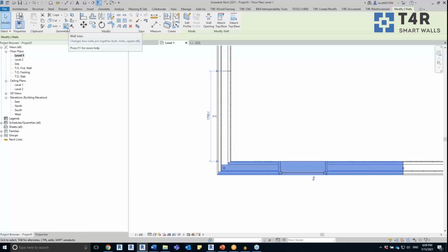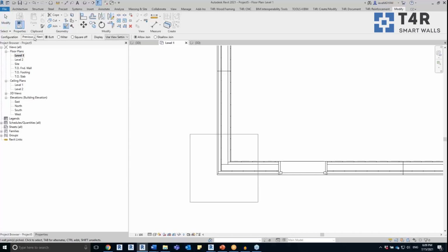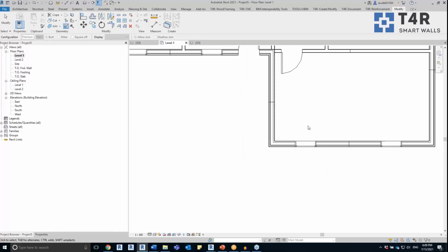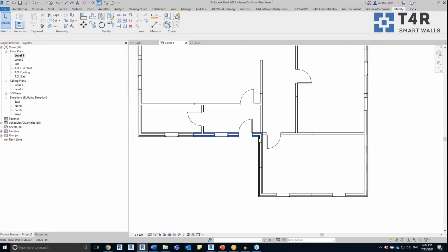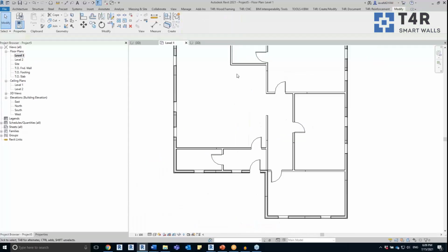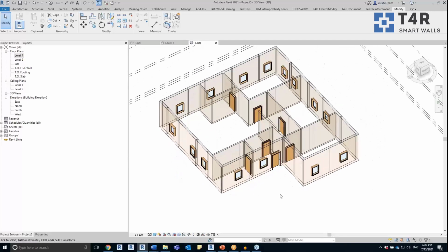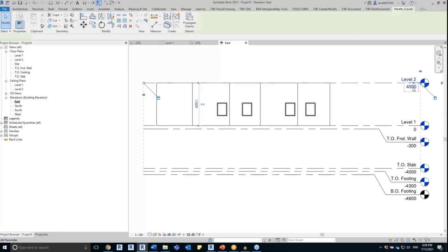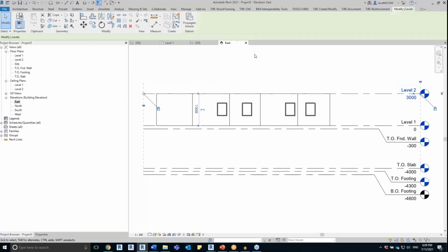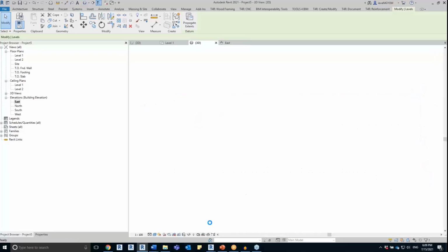So in the Modify tab, you have an ability to modify that as well. In the Geometry Wall Joints, I can click on it and you can see that I can change the wall joint. So that's important because the software will identify the longer and the shorter walls. So I have this connection created correctly. All of the T connections are here. I have some free start connections. So everything will be framed as I will predefine in the configuration. And that, I think that's all that I wanted to say about the modeling recommendations. And I will just quickly lower my level a little bit like this.